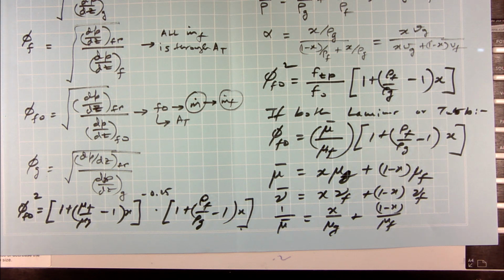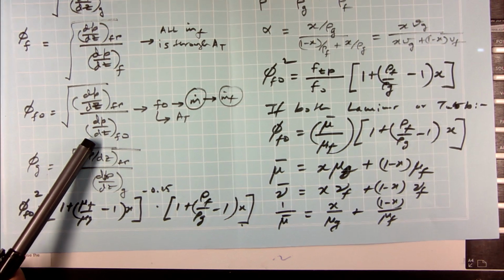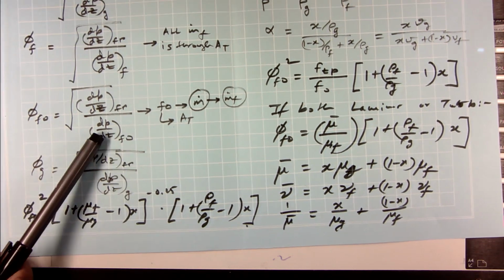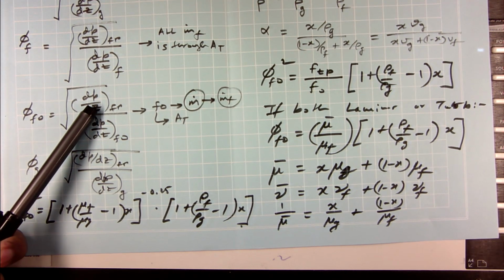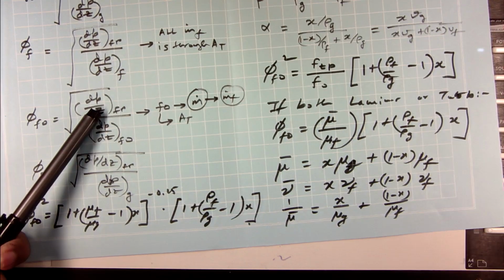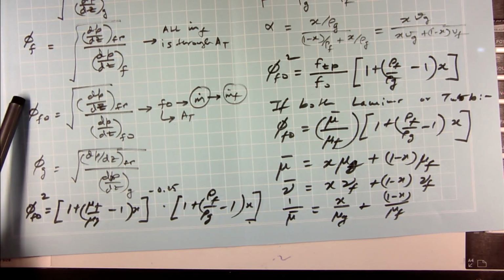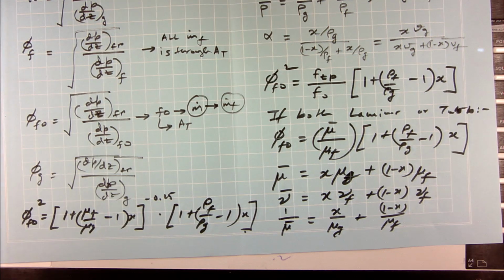Now, what is the beauty of this method? If I know the value of phi f0, it is very easy to calculate dp/dz f0, it is a single phase flow, is it not? So, I take this to the other side, I multiply these two, and I immediately know the frictional pressure drop, because that is the biggest enigma, figuring out the two phase frictional pressure drop. So, this gives you a very simple way of calculating it, but you are not able to use this homogeneous flow equation all the time, particularly when you have stratified flow.